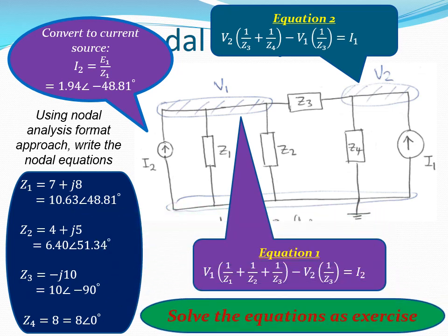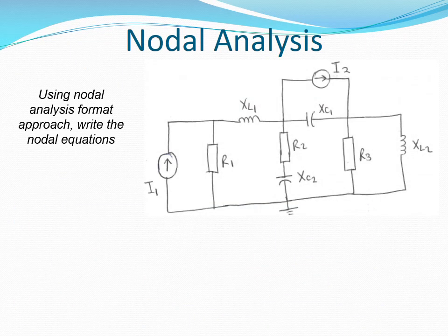As an exercise, substitute for Z1, Z2, Z3, I1 and I2 using the actual values. Then solve the equations for the nodal voltages. Another example, we want to use the nodal analysis format approach to write the nodal equations.